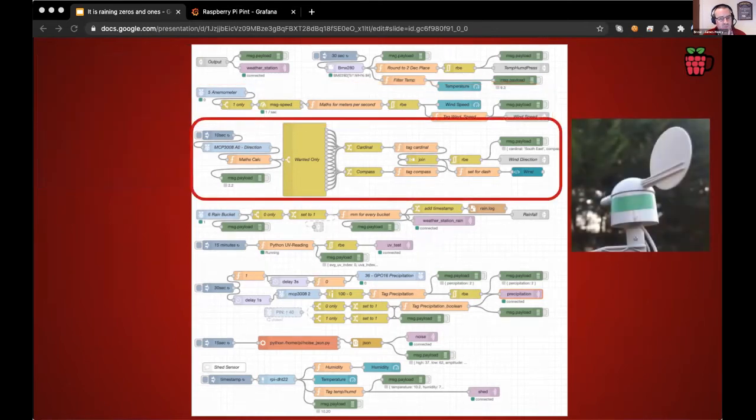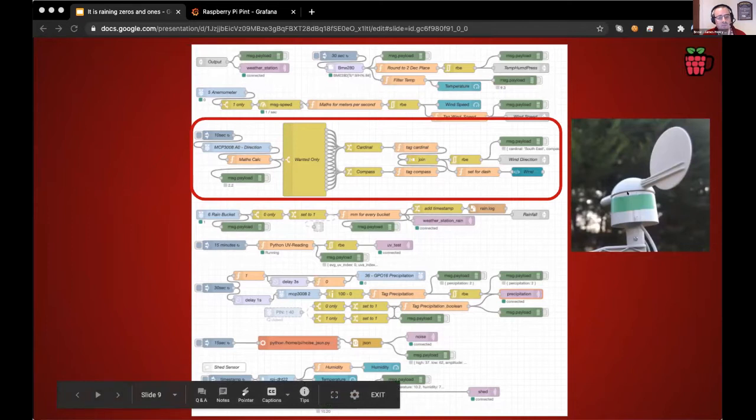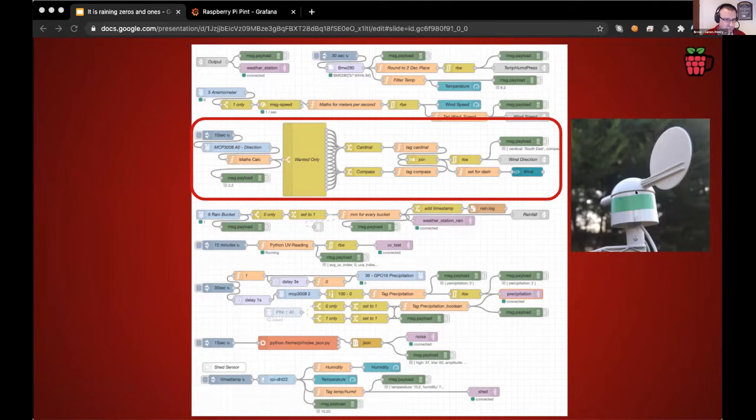Next up, slightly more complex, was the weather vane. So there's a resistor network on the underside of there. So that's spitting out obviously a different value depending on where the weather vane is pointing. That's been read into the A to D chip here. So basically I'm probing that every 10 seconds in this example. And that's spitting out a value from 0 to 1024. So there's a little bit of calculus in there just to try and round that up into the right place.